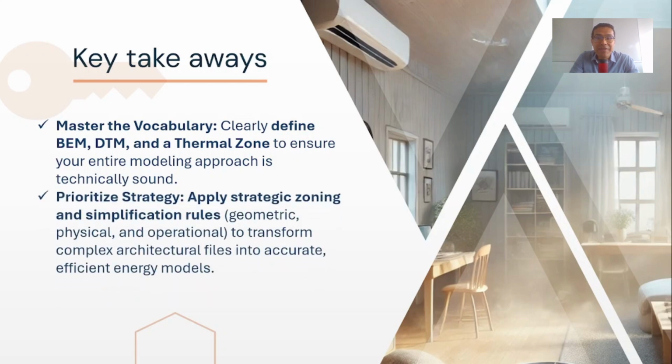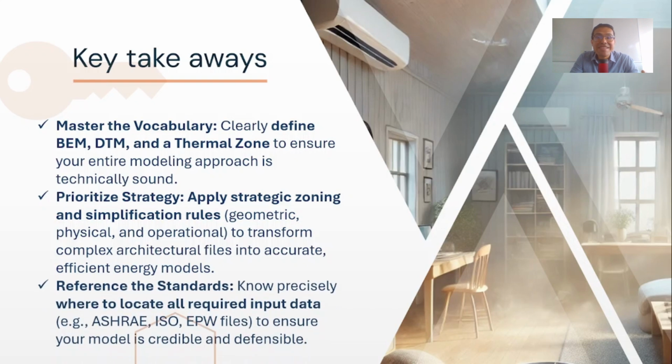Second, prioritize strategy. Don't just import and run. You must apply strategic zoning and simplification rules, geometric, physical, and operational, to transform that complex architectural file into an accurate, efficient energy model that saves you time. And finally, reference the standards. Always know precisely where to locate all required input data, from ASHRAE and ISO handbooks to standard EPW climate files. This commitment to authoritative sources is what makes your model more credible and your results more defensible.